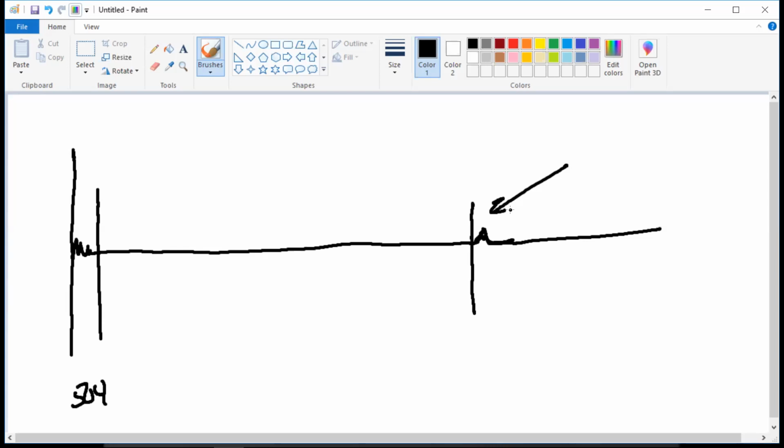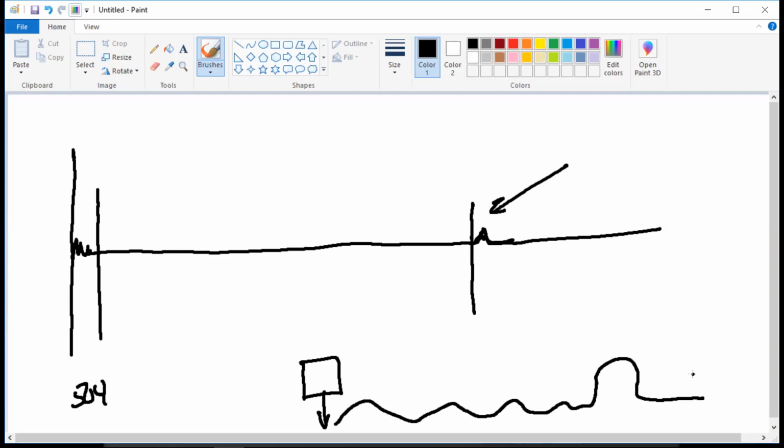Any guesses? Wheel it off. Huh? Wheel it off. That's a good one. What if the open's right here and it's real close? Radar mode is good, but what happens here in radar mode, and you can't tell this, here's where I'm testing from. I don't know how deep it goes. That's footage. I don't know how much my ditch undulates. So that's extra footage. I don't know if it makes a turn and goes around here. So radar mode is the general, get me kind of close.